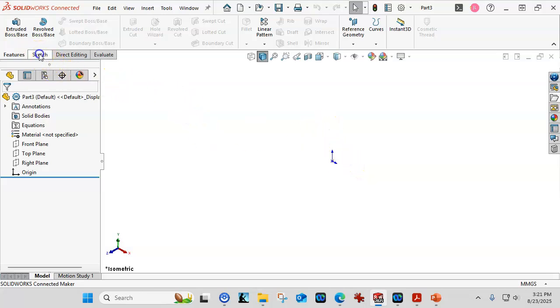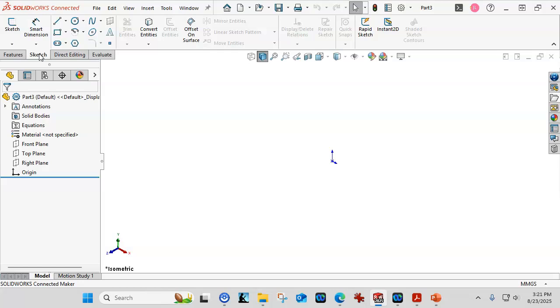So if we are in the Sketch tab, and we will start off with the Sketch tab, but I'm very quickly going to move to the right mouse button because that is going to be the fast way, and that is where I want you to move to quickest. But to get started understanding the process, we have the Sketch. If you like doing the pull downs, just be aware you want to make sure that you're selecting Sketch and not 3D Sketch because that's an entirely different monster.